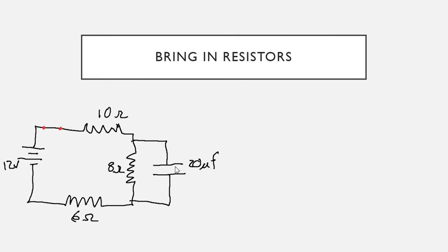Now, there's a couple things, right? How fast is this capacitor going to charge? Well, that's going to depend on how fast the charges can get to it. So these resistors are certainly going to come into play while this capacitor is charging up. But this capacitor will charge up. But the other thing we know is that there is two paths for current flow. Certainly, we could have charges go to the capacitor, and we could charge up the capacitor, but that's not going to happen for a long period of time. Once it's charged, current's going to stop flowing.